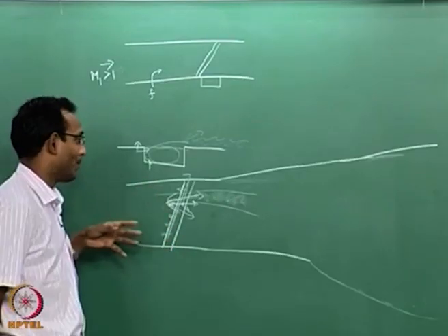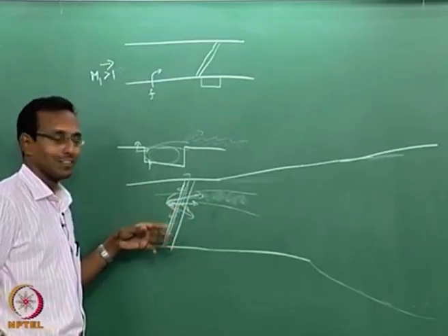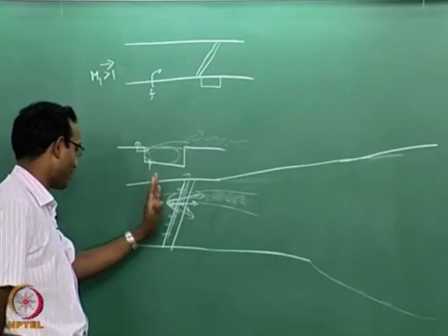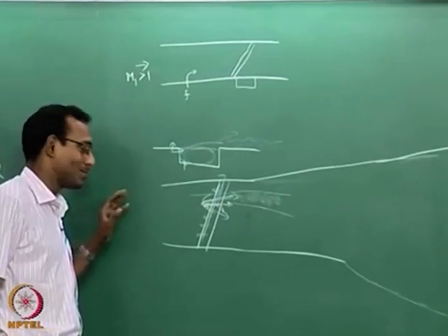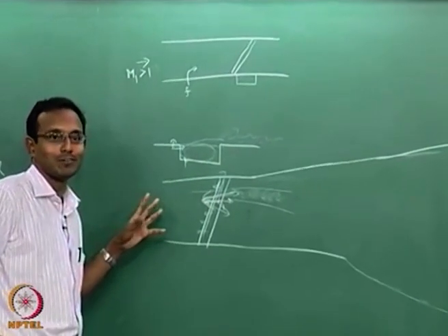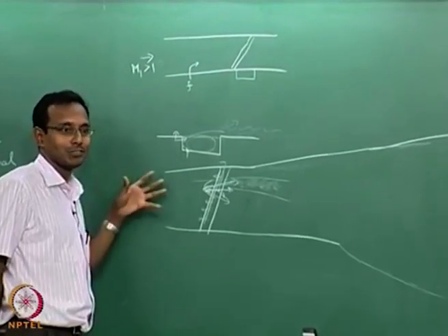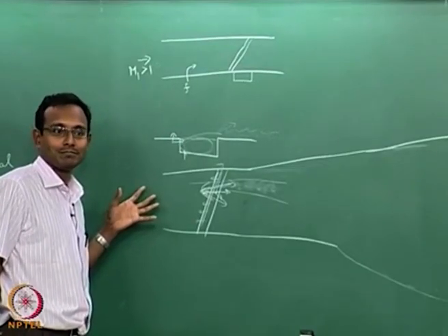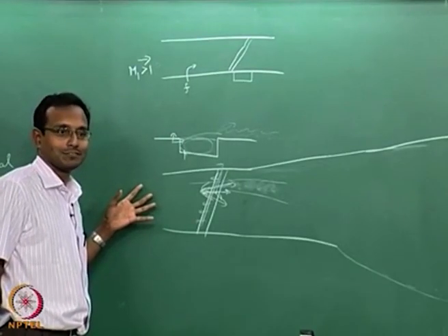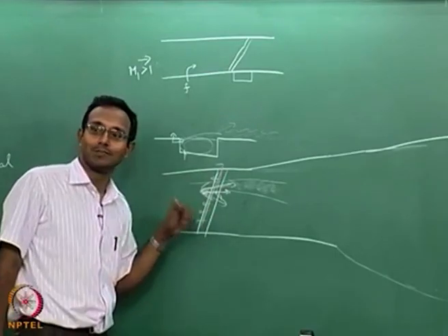And by mistake, if you added a little extra fuel than the choking thing, the whole flow chokes, there will be a shock running straight ahead, and the whole flow becomes unstarted. The combustor is called unstarted. What happens is the flow incoming will become subsonic. It jumps and takes a subsonic solution, and it is no more a supersonic combustor, it is burning subsonic. So they call it unstarted condition. That will start happening if I by chance do that.